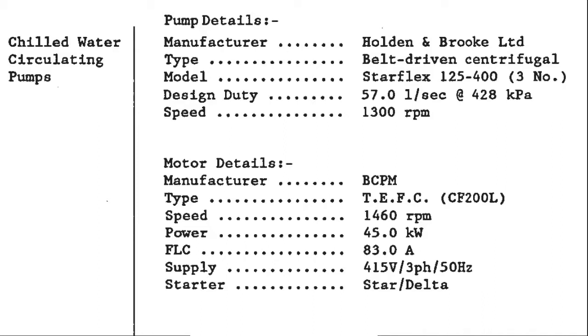Of course, if you haven't got the pump installed yet, you're in a design phase, then you can also use these formulas to determine what the performance will be. So these formulas will give us the values of the pump performance curve. Do remember that these calculations will only give us theoretical values. The actual performance may vary from these, and certainly the older a pump gets, the larger the discrepancy becomes between the theoretical and the actual. So you might need to add on a correction factor to adjust these. But for everyday purposes and for your studies, this is fine.